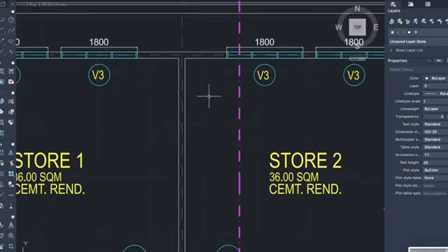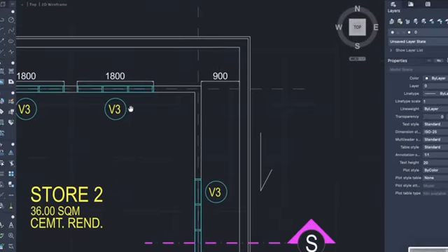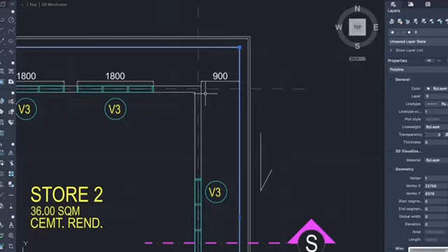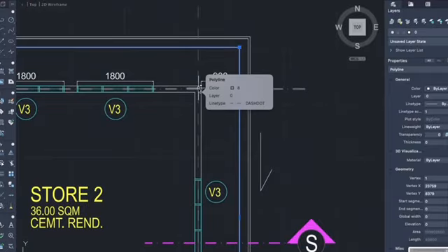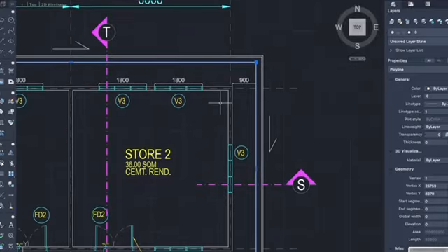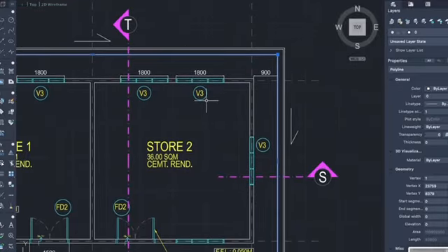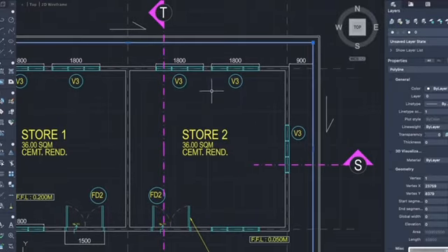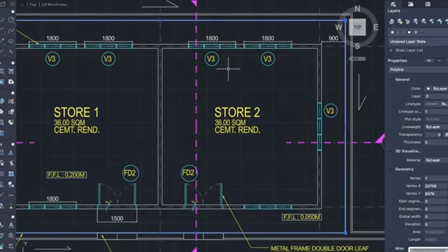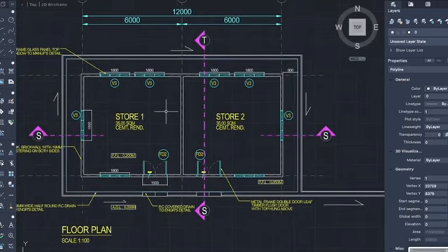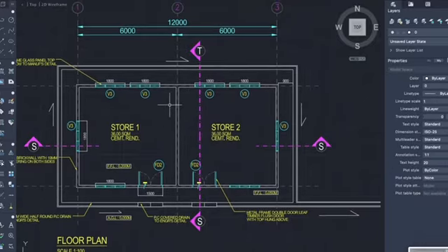After completing the walls, I drew the apron around the building. I offset 900 from the outer wall with the required distance to create the apron. Then I used trim to remove the unnecessary lines so that the apron follows the shape of the building properly. Next, I created the drain, which is the covered drain around the building.